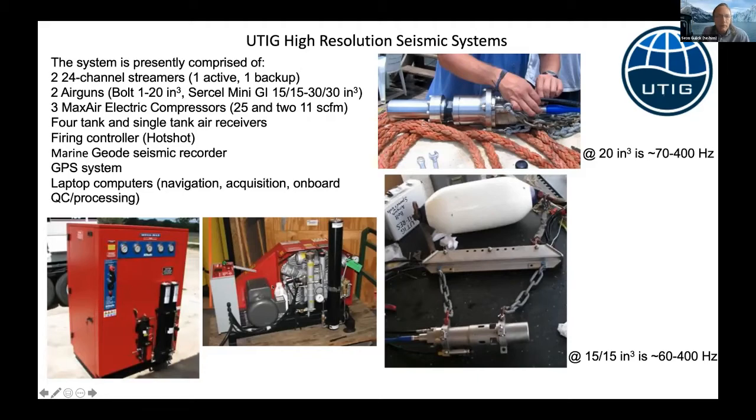We have several different compressors. We've got 25 and 11 SCFM compressors. We have two of the latter. These are all electrical compressors. The 25 one requires 3-phase power on the ship, and the other ones are single-phase 220.